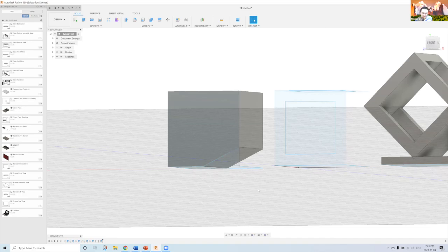For instance, let's say if I rotate this by 180 degrees and this is now facing up, the 3D printer would print very nicely. The top surface would be very smooth, and this surface itself will be printed very smoothly as well. If I oriented this the way it is, perhaps certain 3D printers will be able to manage that if you have sufficient cooling, but others may come out with very bad layer adhesion or just a bad surface finish in general.